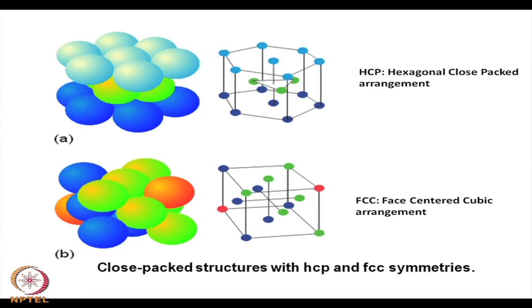There are many systems of slip planes in many crystals depending on the crystal structure, what we have discussed earlier. We have different sets of close packed planes or close packed directions. We have also discussed that all structures are not close packed, there are open structures also. But they do have a slip plane, and whatever plane has the largest atomic density will be called the slip plane.